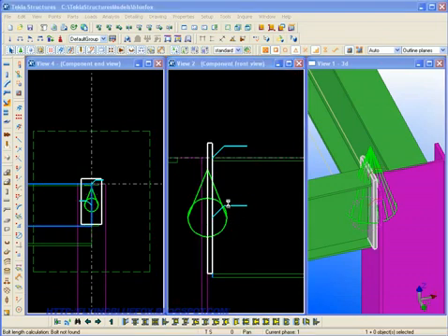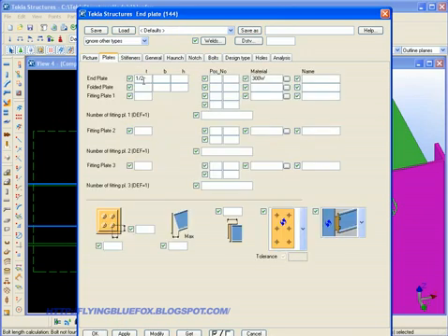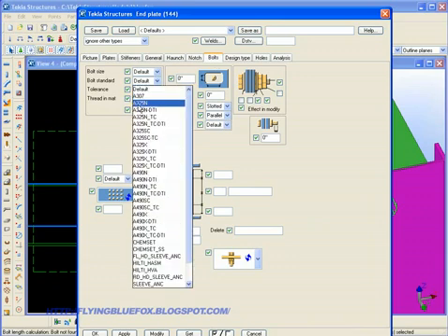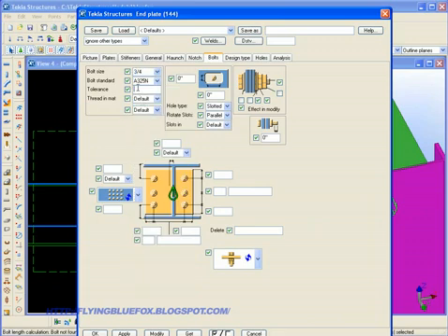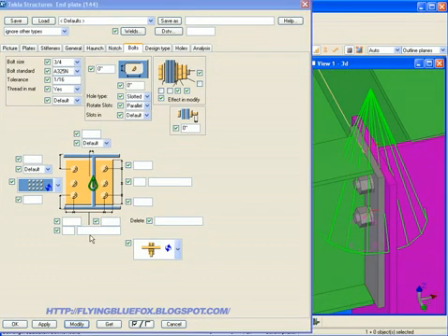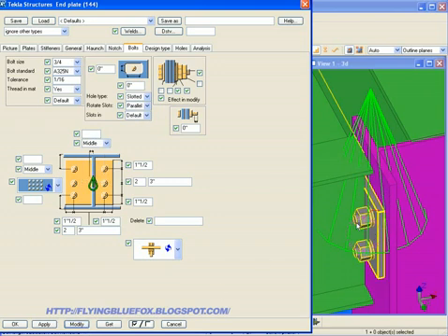Double click on our component again, bring it up, go to our tab here. We made a plate 1/2 inch, material 300, bolt. Go here, change our bolt to A325, 3/4 bolt, 1/16 thread, yes. Modify. As you can see, the bolt shows up now. Let's make our spacing 2 bolts, 2 bolts, and 3 inch apart. Edge distance is 1.5, 1.5, 1.5. Pick the center, so it moves everything to the center right there.